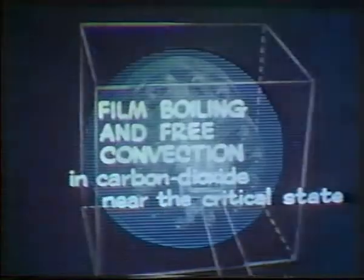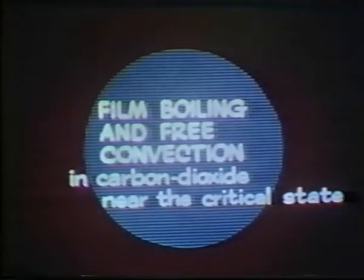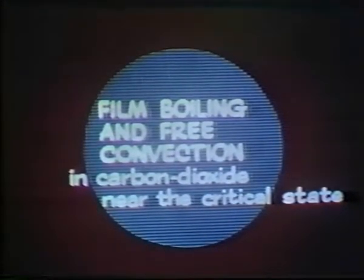This film presents high-speed movies of pool boiling and free convection from a wire immersed in carbon dioxide. The carbon dioxide is near its critical state of 73.8 bars and 31.1 degrees Celsius. Below the critical point, there may be free convection, nucleate boiling, or film boiling. Above the critical point, only free convection is possible.